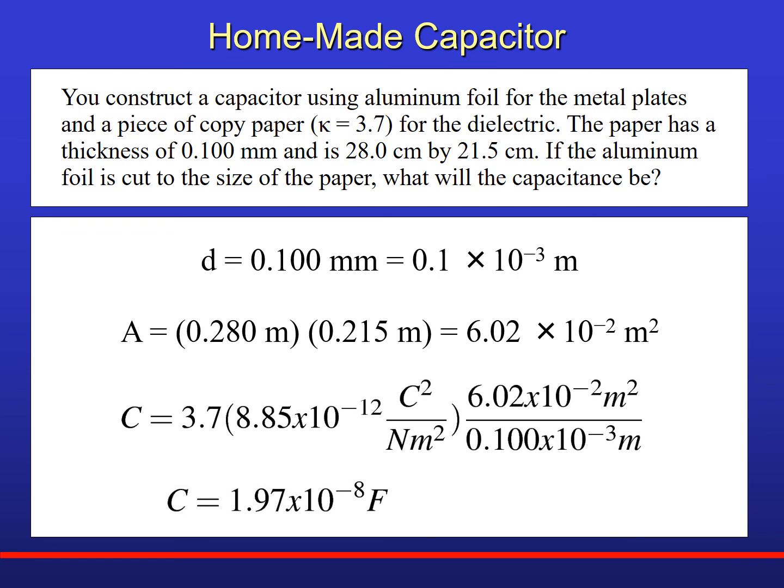Well, if I divide 10 to the minus 8 by 10, I'd get 10 to the minus 9. But in order to divide that by 10, I have to reverse it by multiplying the other part by 10. Right? You're basically doing nothing. You multiply by 10, divide by 10, you've done nothing. But multiplying the 1.97 by 10, you get 19.7. Dividing the other part by 10, to the minus 9, you get nanofarad.